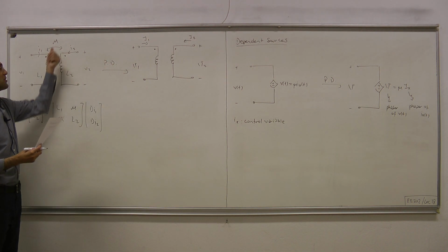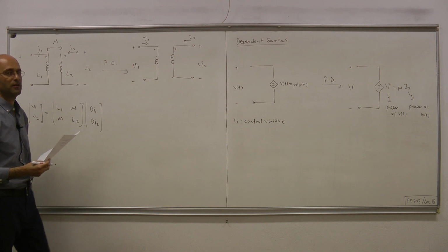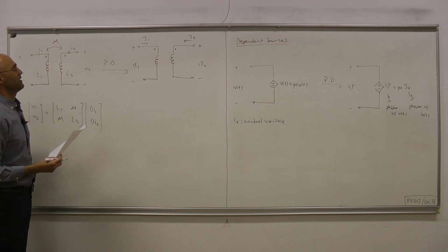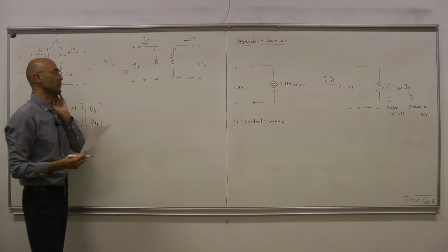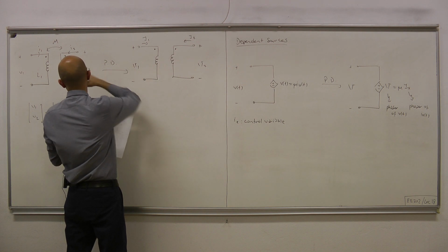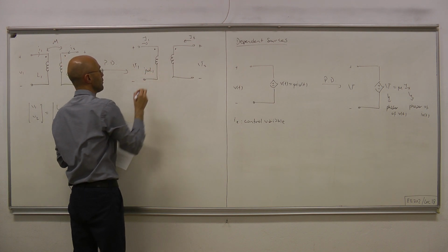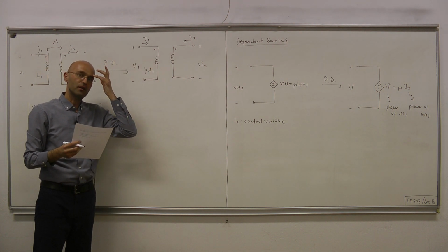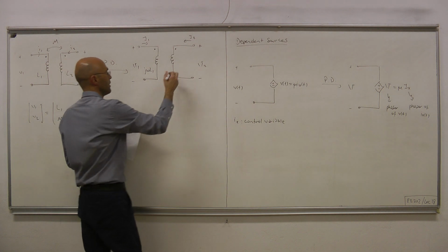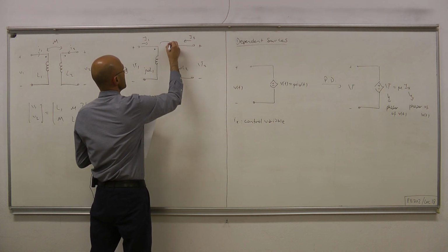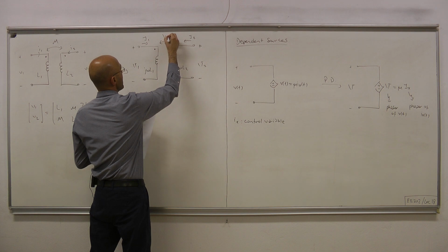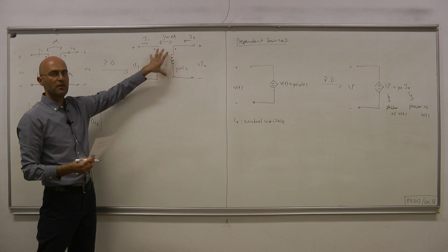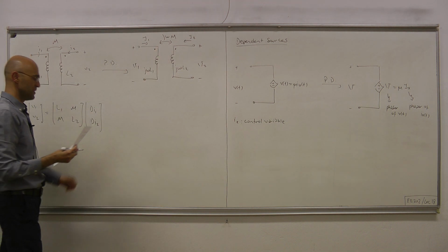Now, as for inductances, self-inductance and mutual inductance, we replace them by impedances and, well, in a sense, mutual impedance. So what we mean by that is, instead of L1, here we have j omega L1. Omega is the frequency of operation of the circuit which this coupled inductor is part of. Here we have j omega L2, and here we have j omega M. And now the question is, what does this picture tell us? It tells us the following.